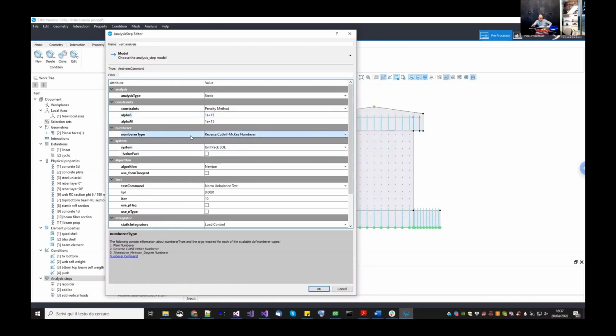In the example that I've done before, I've only used OpenSees sequential. Okay. Now in this example, you will see it when you download it. I'm not using OpenSees sequential. I'm using the parallel version of OpenSees, but not because I want to do parallel analysis. Since this model requires more computation than the other, I will show you that you can use the parallel version of OpenSees, not because you're going to do a parallel analysis, because we will talk about parallel analysis Wednesday, but because the parallel OpenSees has a new solver, which is called MUMPS, that is much faster than this one.